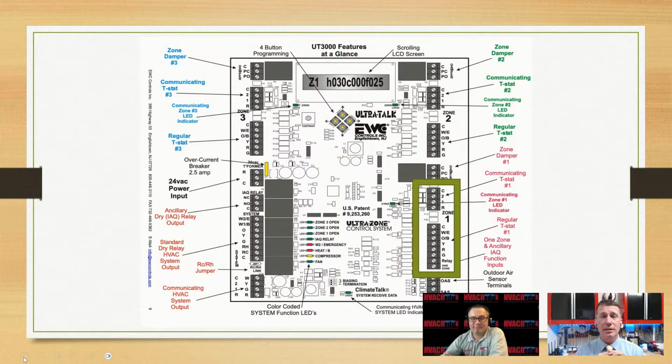On a communicating system, right, it's got to be a communicating indoor unit and a communicating outdoor unit. You can use either a communicating thermostat or a legacy thermostat for your zones. But this is only for the Daikin network. There you go. I'm surprised that we don't have these for every other manufacturer. Part of that, talking to my friend that's the engineer for this board, he says the manufacturer just won't give us all of their data for what language they're speaking.